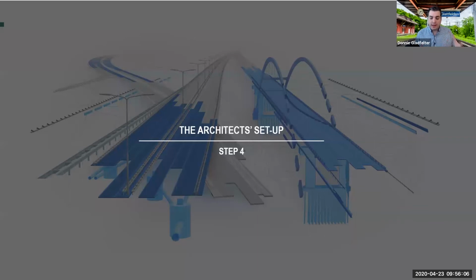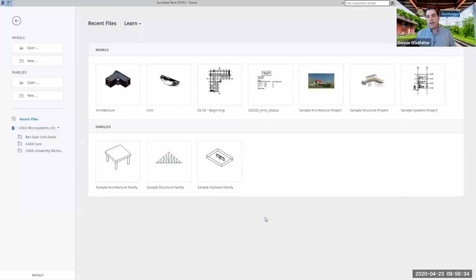And so we have yet another challenge to face here, and that is, how can we, in a managed way, bring my civil site to the Revit model? This is kind of a little bit of a riddle. We could import the shared reference point directly into the architectural model, but again, we're going to exceed that 20-mile limit. So how can we skirt around this issue? My solution for this is to create a new Revit model.